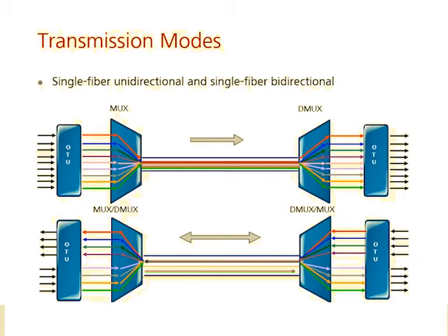It's very hard to use this amplifier. So in our real network, single fiber unidirectional is widely used for high capacity, long distance. A single fiber bidirectional system can be used for some small capacity, shorter distance applications because it's very cheap, and it can also supply WDM technology for some lower-requirement places.